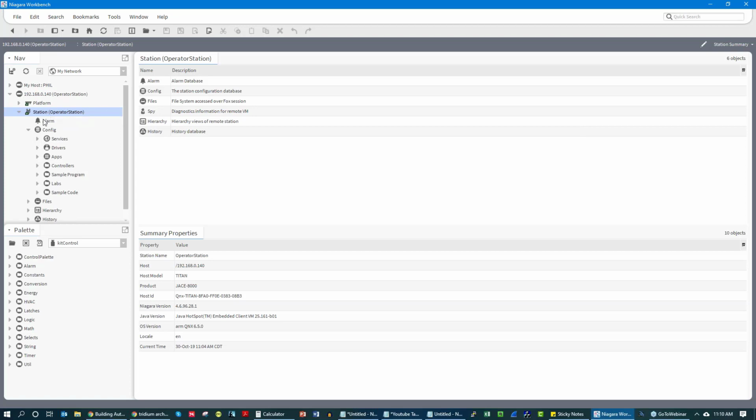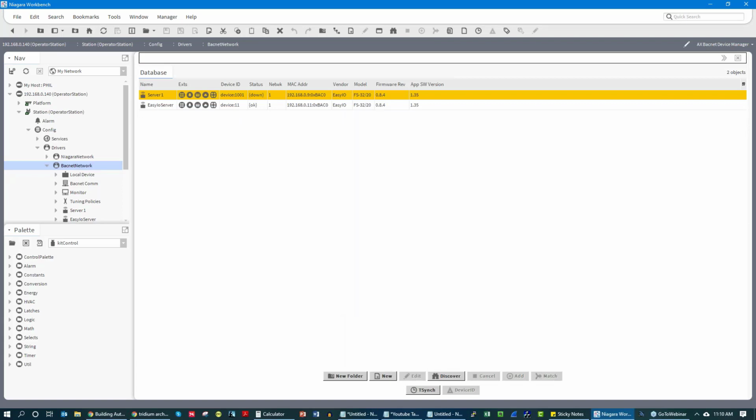So remember, I said I have a supervisory device, and my supervisory device uses a field trunk in order to go and pull in controllers, and these controllers are consuming inputs and outputs from devices like thermostats and actuators and pressure sensors, etc. So in Niagara, you have to add a driver to allow it to consume a network. In our case, we've added a BACnet driver because BACnet is one of two protocols that you will primarily use in building automation, and those are BACnet and LON.